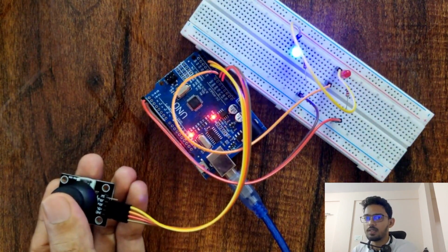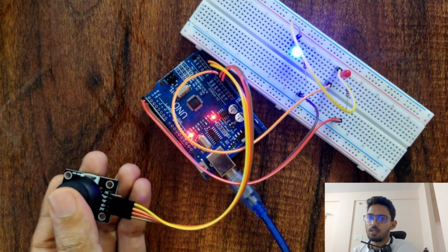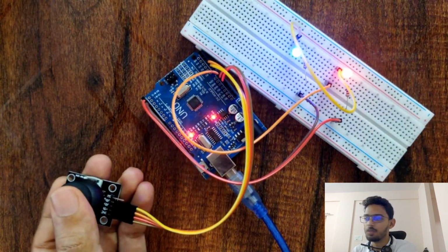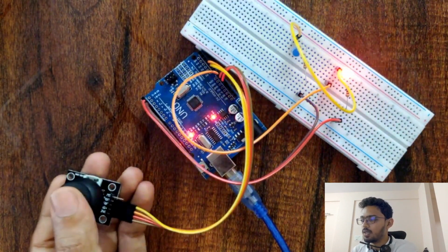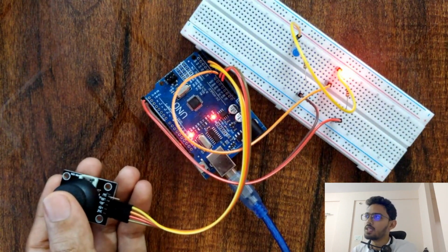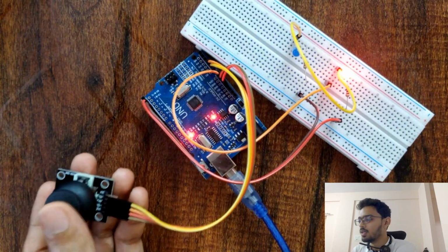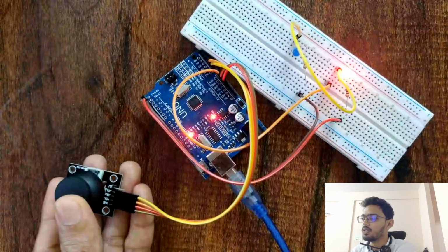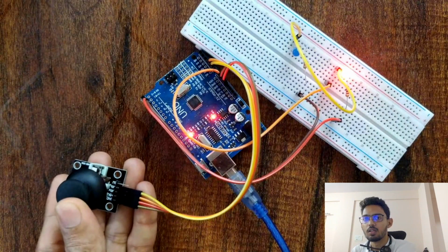Then we go to the negative cycle. The behavior is inverted again. The blue LED starts glowing for a longer time duration, and if we keep on going further negative by moving the joystick in the -y direction, again we see the change in duty cycle until at the very end only the red LED glows, in which case the output of the comparator would be 1, and therefore the blue LED is low at all times. This is how, by changing the duty cycle using the joystick, we can vary the frequency of blinking of the LEDs.